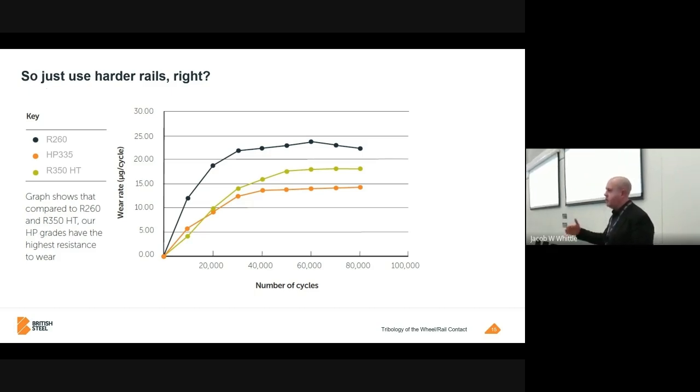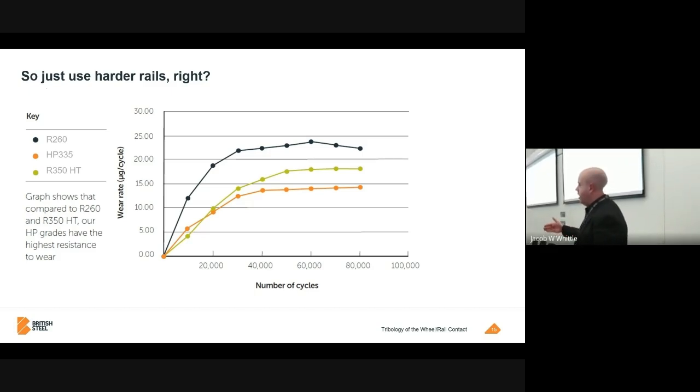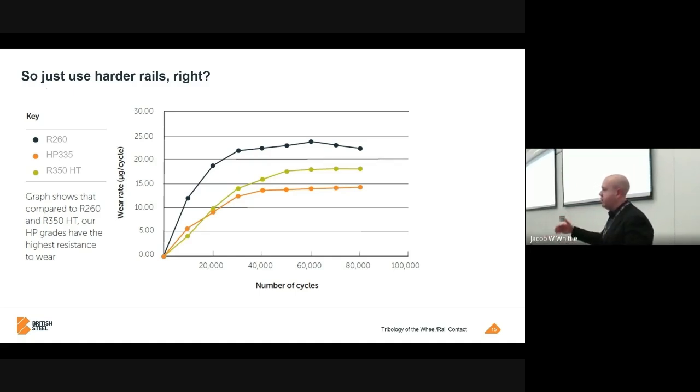So hardness is not always the answer, and it's something that we don't quite understand. I think, dare I say, we've been a bit lazy in tribology up to this point, just assuming that hardness is the answer to everything. Hardness is just a number, and if you think about Archard's wear equation, you stick a, dare I say, fudge factor on the front of it.